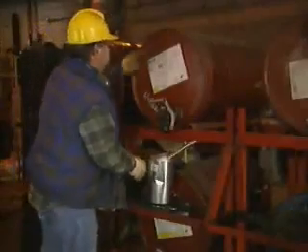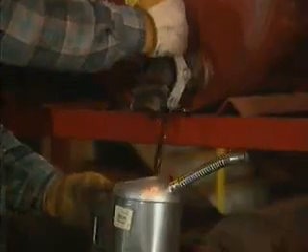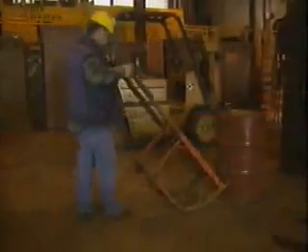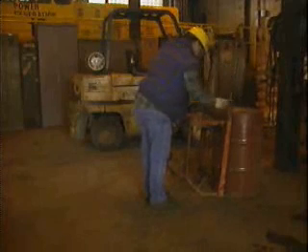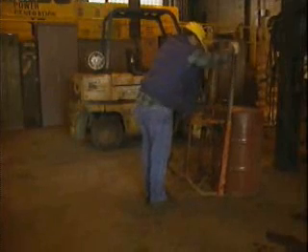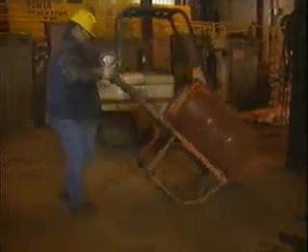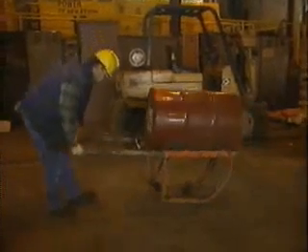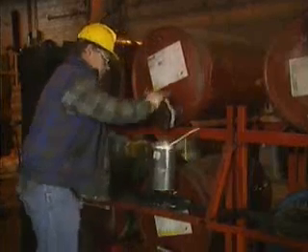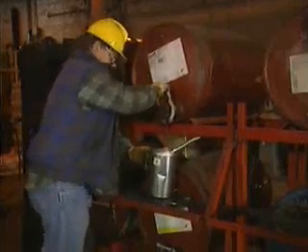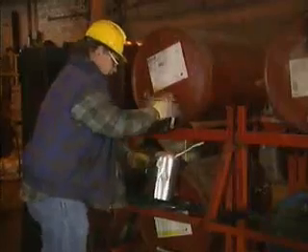Another way to dispense oil from a drum is with a spigot that has a leak-proof valve. The drum must be positioned on its side. Sometimes a drum with a spigot is placed in a rocking frame. To dispense oil from the drum, the frame is rocked forward so the drum lies on its side. The drum may then be left in this position until it's empty, or if necessary, it can be rocked back into the upright position. With the drum vented, open the spigot and withdraw the oil from the drum. When the desired amount of oil has been withdrawn, close the spigot and the vent cap.